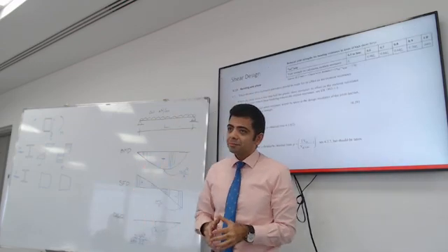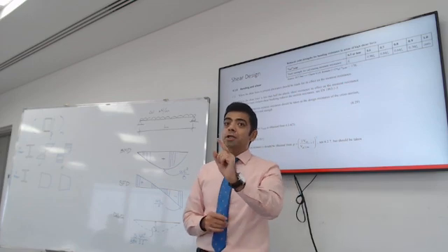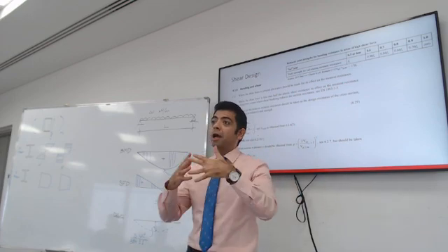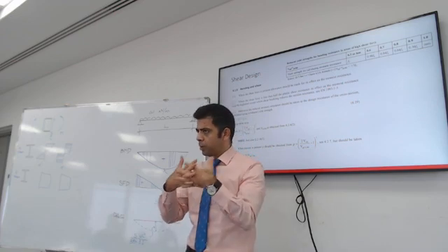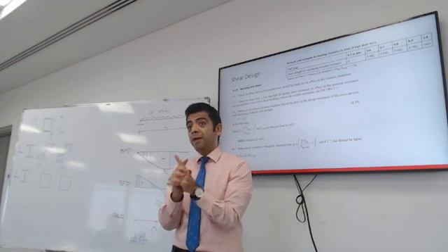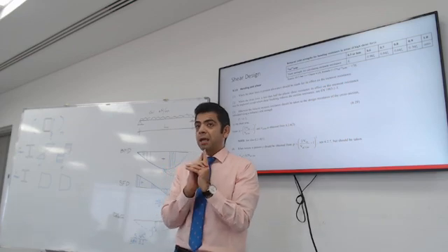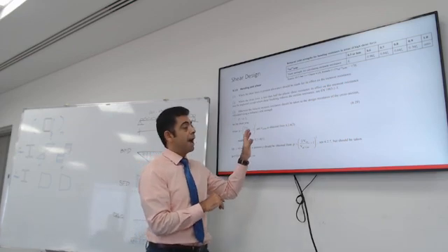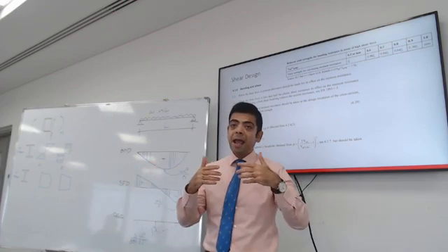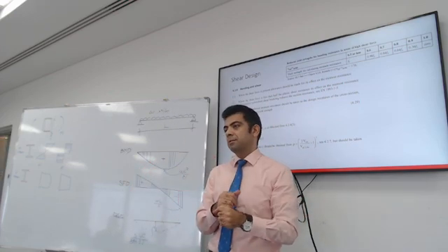Now, there is a critical issue that could result in an under design or a problem in your beam. Your beam could fail in a certain case if you have bending and shear at the same section.